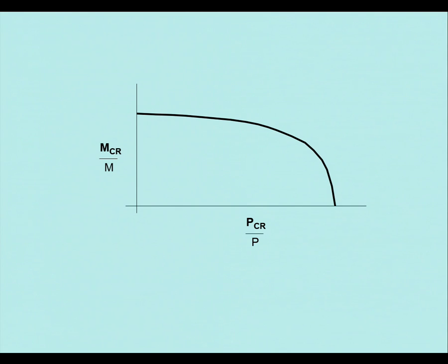If I've got here 0 bending moment, I can increase the pressure to here, so P equals PCR, before it will fail. So as long as I stay inside that ellipse, it won't fail, theoretically. But if I now put in another line down here, and say I'm going to stay in that, that's the safety factor.